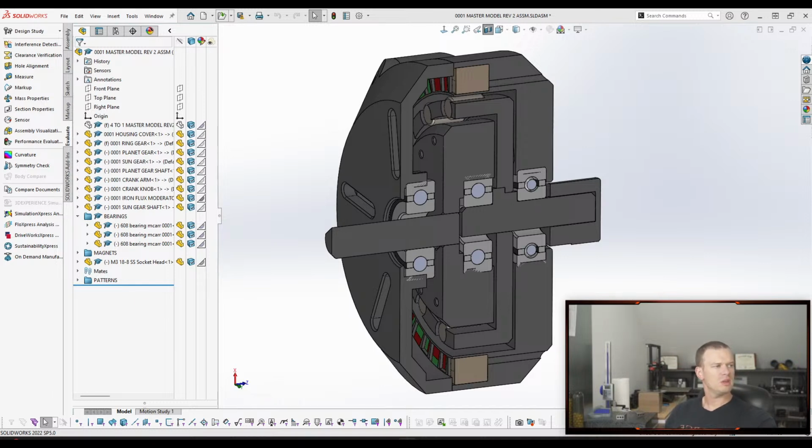Yeah, the advantage of having multiple people working on it is that you give them the handle file and they can make edits to it, or they can edit their part off of it, but can't change the original. It's the same with the derived sketch, right? You can't edit a derived sketch. You have to go back up to the parent file and then edit the sketch within there.